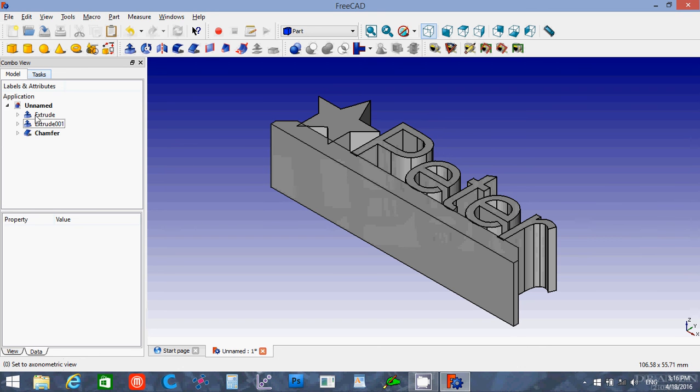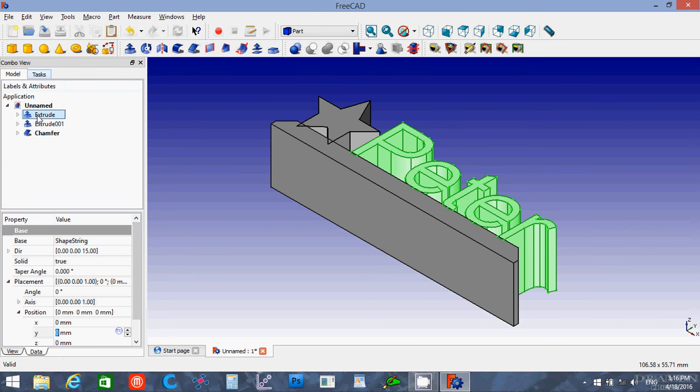And what you want to do is, okay, there's two differences in 3D printers that I've noticed when I do things. If I don't combine everything, fuse them into one part, what happens is that the printer will end up, for MakerBot printers, anything that's based on a MakerBot printer, I found that it will treat every overlapping part as a difference when it 3D prints. So, let me see if I can find the pictures.